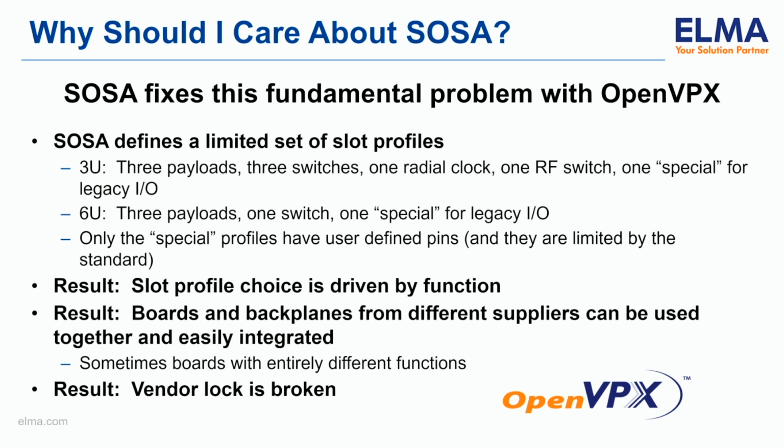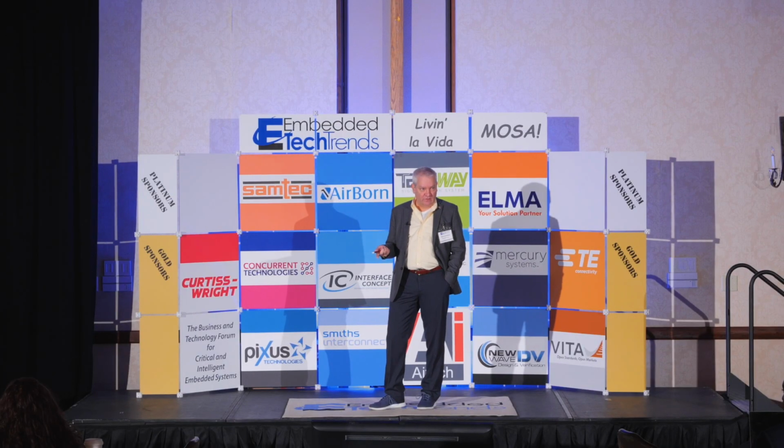So how does it do that? By having a limited set of slot profiles. Specifically, if we take a look mainly at the 3U, there's 3 payloads, 3 switches, a radio clock, an RF switch, and then one special one for collecting kind of legacy I/O. That one's special in that it's the only slot profile that allows user-defined pins, but it's virtually all user-defined pins. And there's some rules within the SOSA community about how those are used.